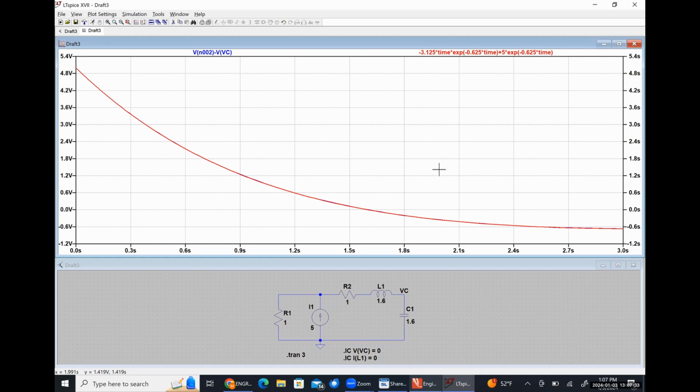What I really wanted to point out to you guys is that we literally cannot use units in our mathematical expression for this guy because it does not know how to interpret this being amps per second. It doesn't like a fraction in the units. For an overdamped circuit, you could always say that this coefficient had a unit of amps or volts where appropriate, and it actually won't even bother with the scaling factor on the right-hand side of the screen. But for a critically damped circuit, you have to explicitly check the scaling factors.